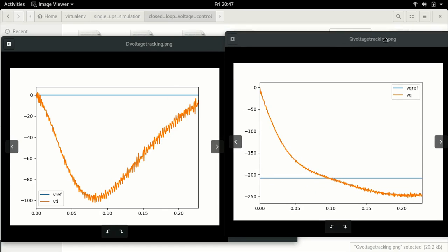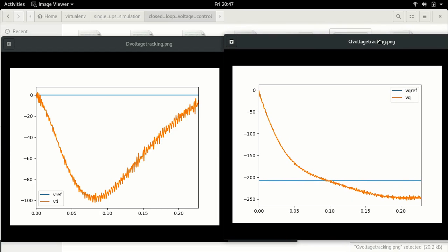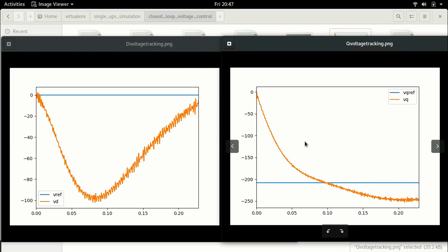As I said before, in almost every PI controller, you need to spend some time tuning your control value. So for example, you look at this, this is the reference, the actual value comes, it decreases, or rather because this value is negative, it decreases, it comes close to the reference, but then it overshoots. This is an overshoot.